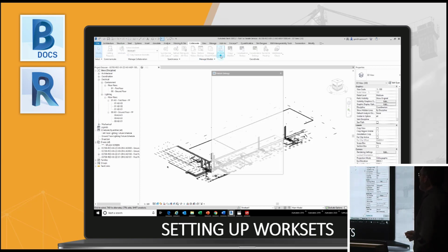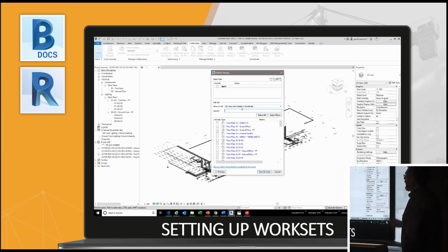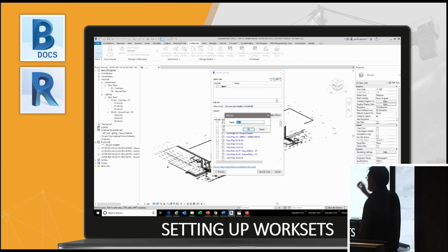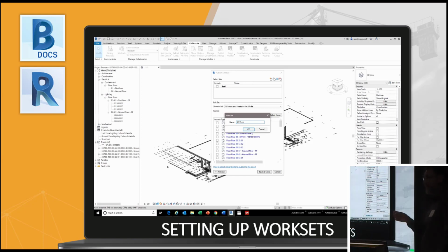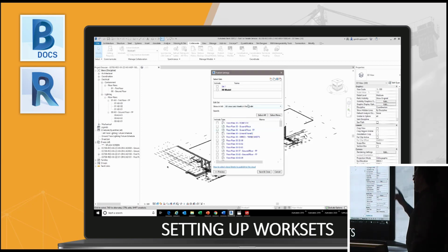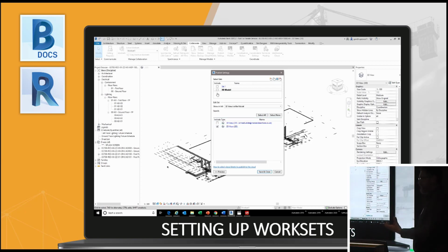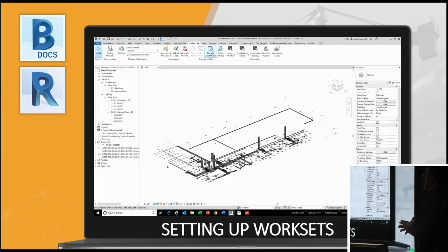As you can see, what it allows us to do is publish what information we want to see inside this. So, for example, we can just show the 3D model, we can show all the views, and we can show the sheets. In this case, I'm just going to show the 3D view, because all we're looking at is coordination here. We're not bothered about the sheets, so I'm just putting a coordinated 3D view that we can send through.